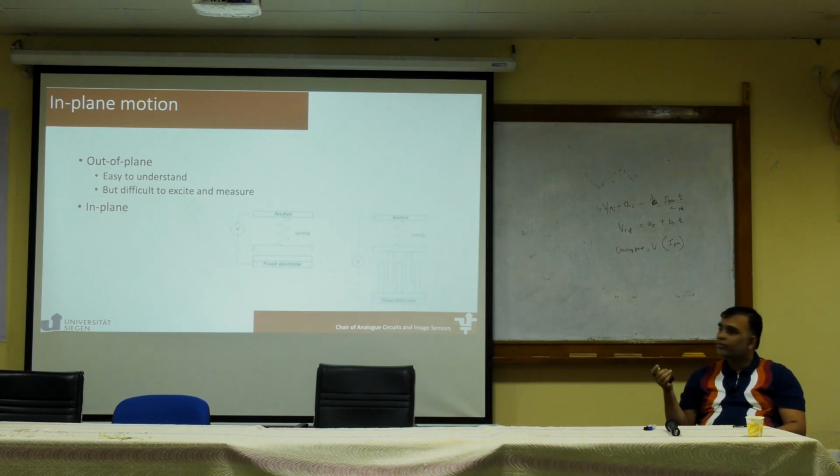So we often make these interdigitated finger-like structures, where we are increasing the total force of excitation by having a large number of such fingers. The principle of operation remains the same. You have got electrostatic pull between the resonators and it's going up and down.